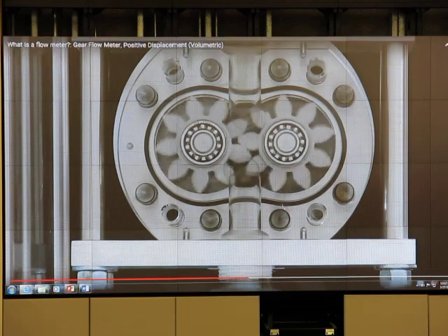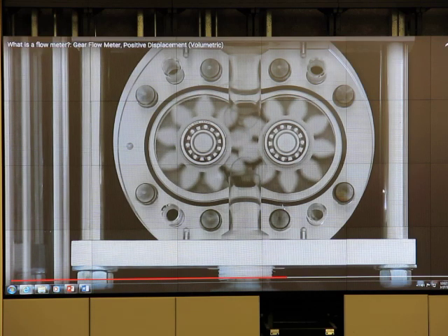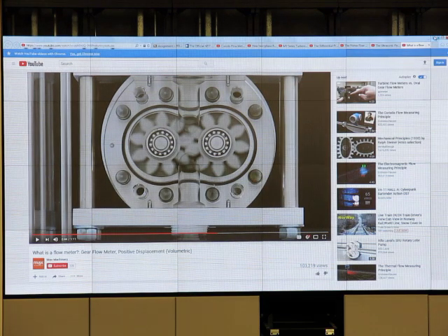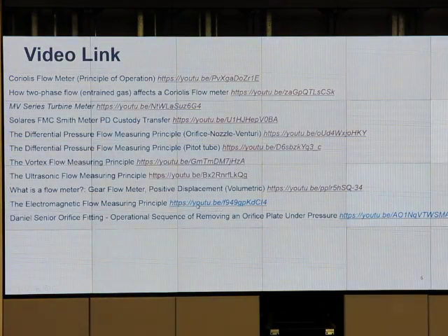You will notice the meter is impervious to intermittent or start-stop flows and changes in viscosity. This is unique to positive displacement meters. So it's similar to a gear pump, right? But for a gear pump, we spin it for the fluid to move. But this one we use fluid movement to make it spin and register how many times it spins. Okay, so this is the positive displacement type. The rotary vane type, the rotary vane flow meter, that is on the lab unit. Okay. Electromagnetic flow.